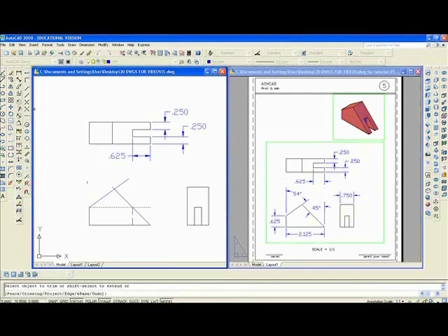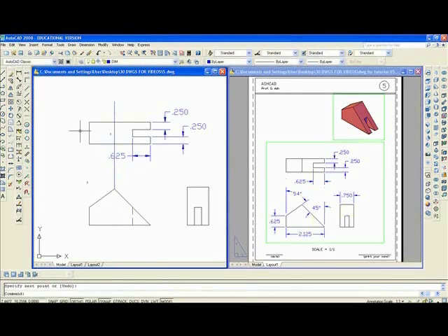and I can erase this line, fillet this area here, match property, because I want everything to be on the right layer. So I want that line to be on layer 1. And I can erase this line and draw a new line from here up, and then trim it. TR enter from both ends.